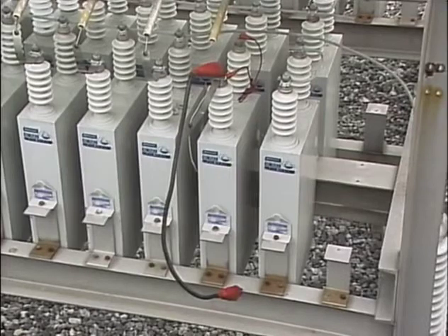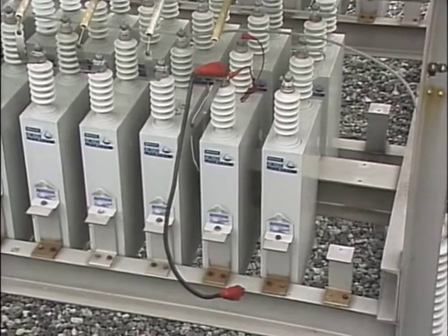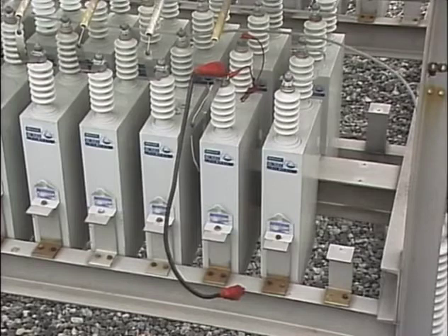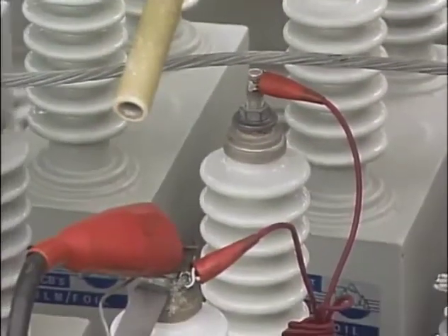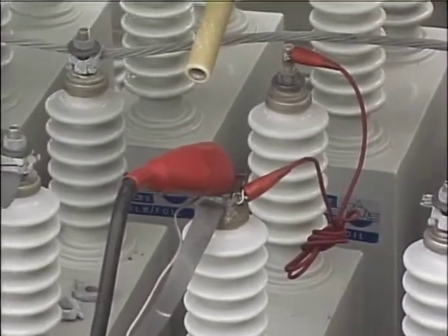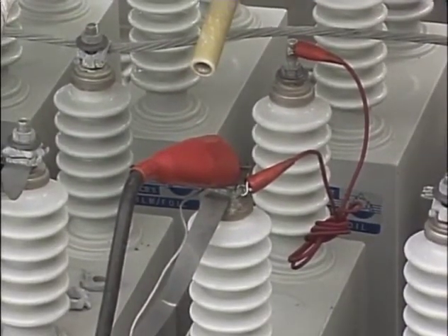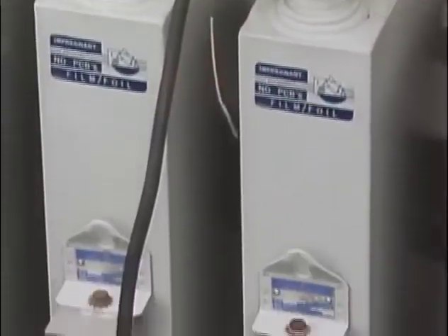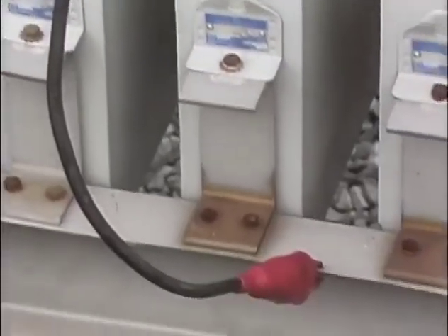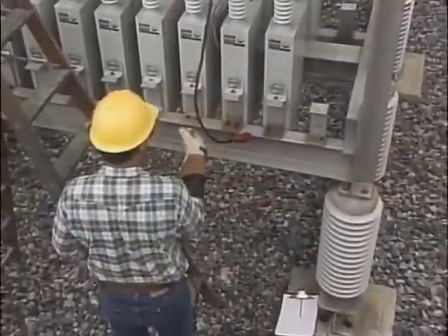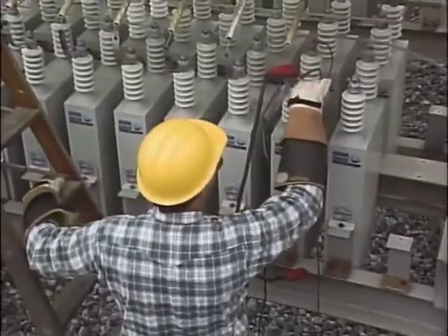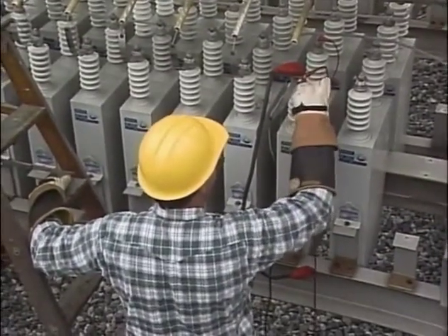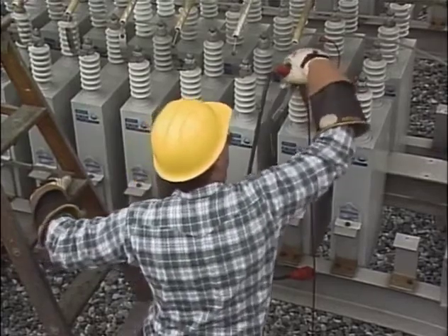The short across the capacitor terminals is kept on. This keeps the capacitor discharged and makes it possible to test the insulation of the capacitor from both terminals to ground. In addition, both terminals of the capacitor are disconnected from the bank so that only the insulators for that capacitor are tested. As a precaution, one terminal is temporarily grounded until the test is started. One lead of the megohmmeter is connected to the capacitor tank. The other lead is connected to one of the capacitor terminals. Then, just prior to performing the test, the temporary ground is removed.